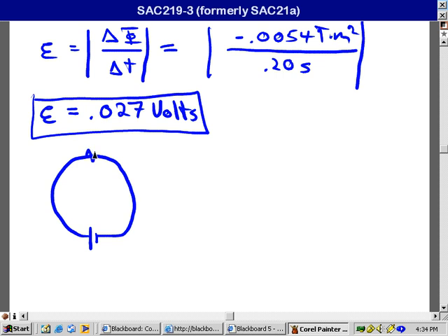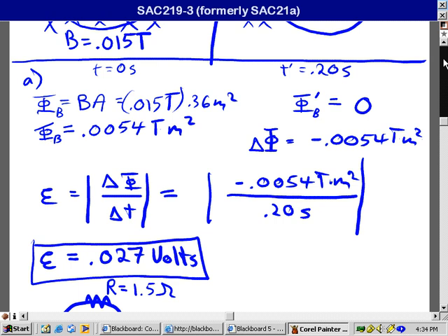It's called the lumped components model. Lump all the resistance of the entire loop into one resistor right up here, where the R is equal to 1.5 ohms. Now, I've chosen that battery direction arbitrarily. I can make this side longer if I have to. Let's see which way the current is actually flowing. According to this model, it's going around that way.